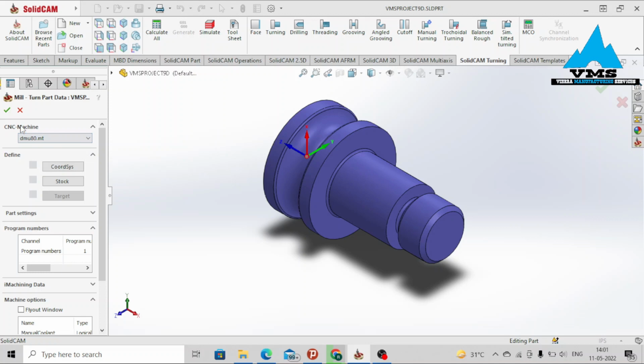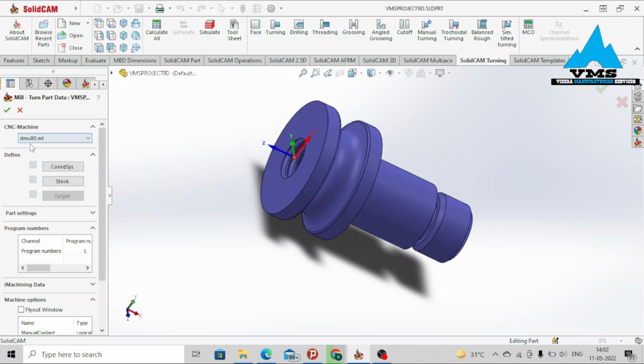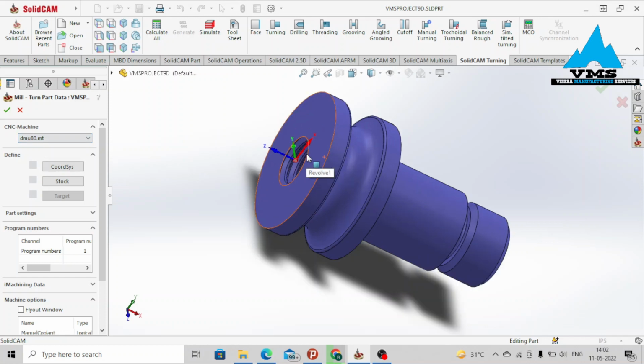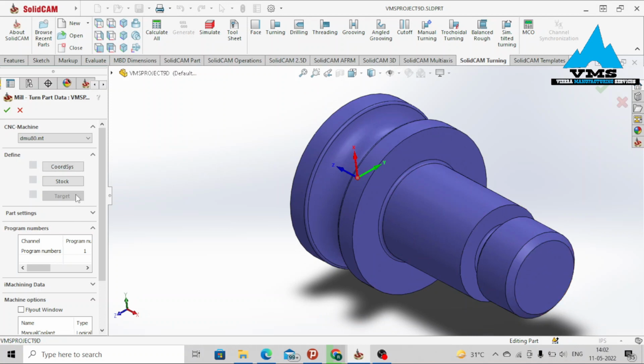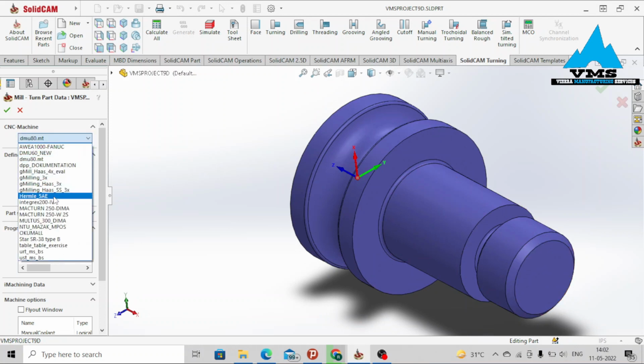So guys, now the CNC machine controller, very important. This CNC controller is actually used only for turning, in the sense that it can only be used for turning and it gives only one offset system. You want to make sure that you have two offset systems. By default, when I'm using this default CNC controller, it will give me only one coordinate, that is at the surface. But when I'm using MIL10, I want to make sure that I have two coordinate systems, one at the surface and one at the back. Hope you got that. So you want to make sure that you change this controller.